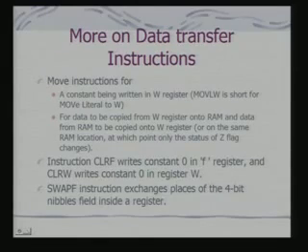In fact, we can also have arithmetic operations done with the immediate operands involving W register. Also, we can do data movements, in the sense that data can be copied from W register onto RAM locations as well as vice versa. So, these are the basic data transfer operations that are supported in the PIC instruction set.